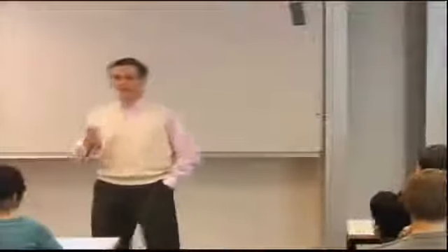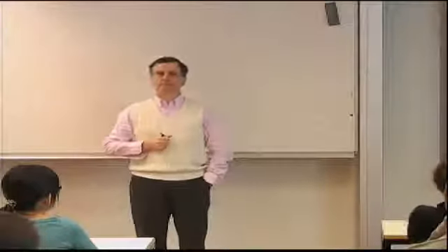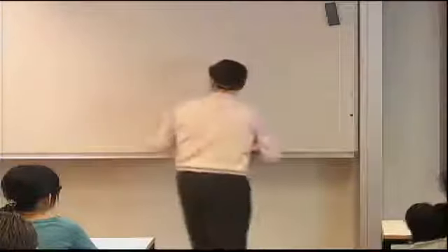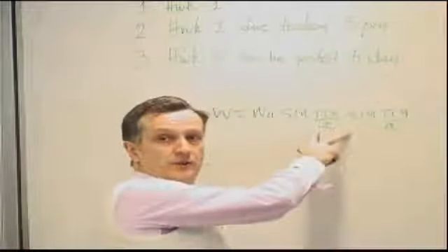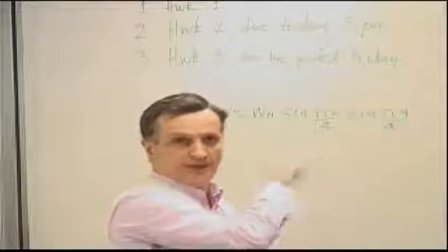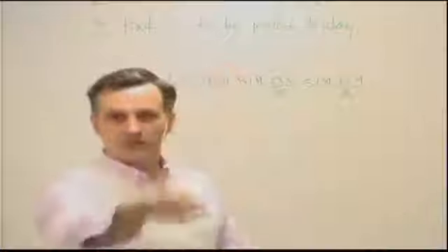Now you might say, okay, is that good or bad? Yes? Are they now both in the same mode, let's say? Yes. In fact, because we assumed the solution to be in the form of W is W11 sine pi x over A sine pi y over A, by construction we have assumed a single half wave. Now it turns out that for most aspect ratios up to 1.5, this is correct. It will be a single half wave.